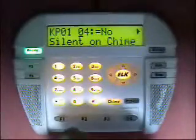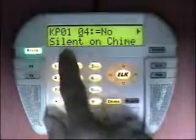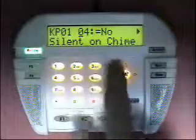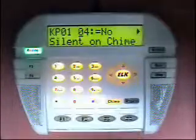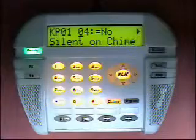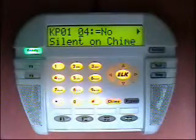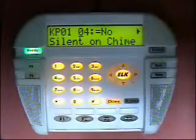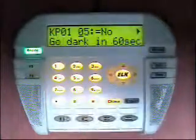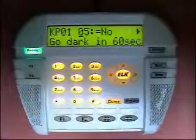In this case, the keypad will be silent on chime if the answer is yes, but in this case it's no. So whenever a zone violates and the M1 sends out a chime signal, the keypad will enunciate with a chime.